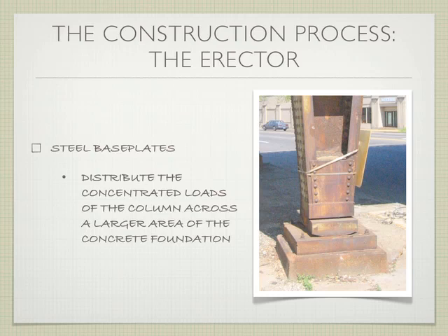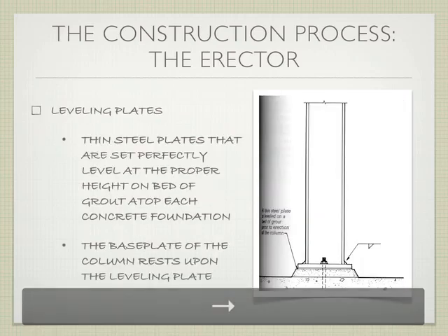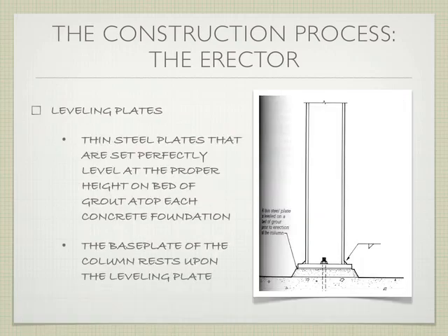And they're going to vary a bit. We can go on the smaller scale into what's called leveling plates. A leveling plate is a thin steel plate that's set perfectly level at the proper height on a bed of grout atop each concrete foundation. So the leveling plate that we're talking about is right here. You guys see that?